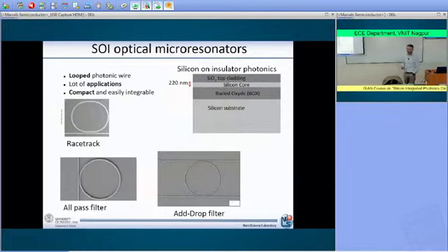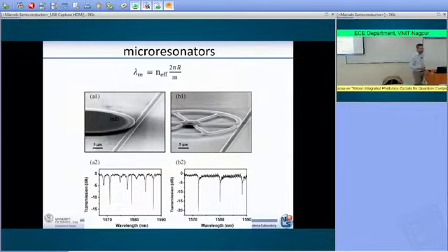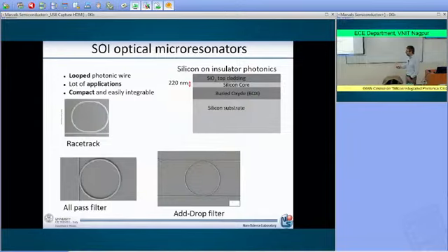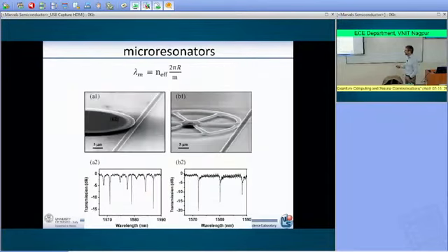Those are a few waveguides that we have fabricated. But then you can also play with the kind of structure that you can fabricate. Here is another example of those waveguides. You see that they are microresonators because you see the length scale here, a few microns. And in this case, you have a waveguide on a plane, and then on top of this waveguide you have a disk. Okay? So instead of having a lateral situation where you have the waveguide on the same plane as the ring, here the waveguide and the disk are on two different planes.